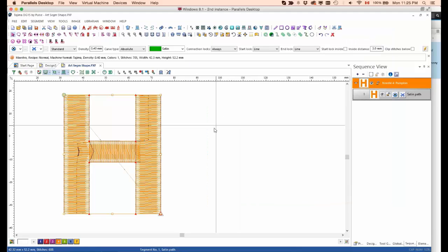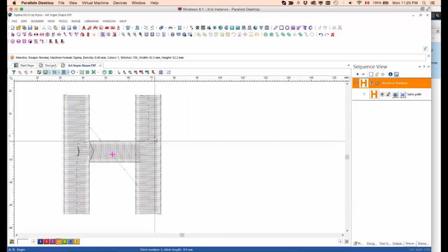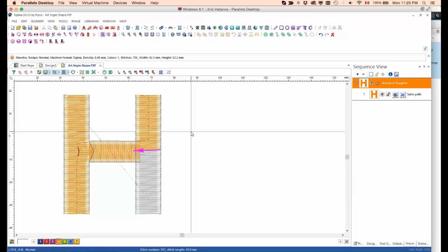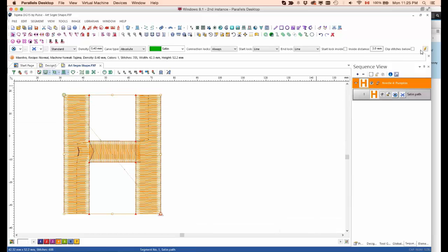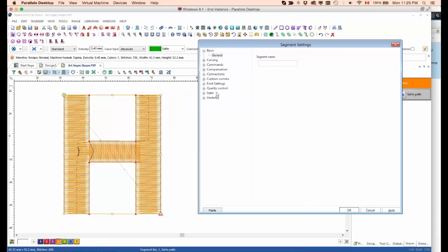Actually, before I do this, let me first show you how the stitches are going to affect here. You see it's traveling here, and here now you have this problem happening. The gap will happen right there, right there, right there. Now if I select the segment and I apply the fill gap, which again is in quality control, I select the add fix gap, and here you have two settings: repeats and angle tolerance. Let's keep repeats on 1 for a moment.